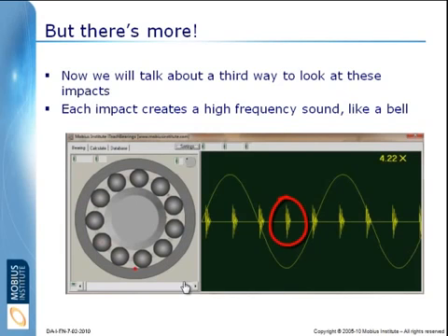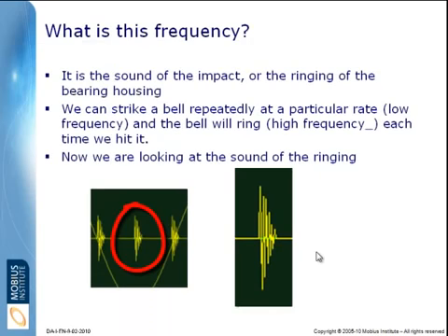Now, the third way is to look at or listen to the sound that is made when a ball hits the defect. We can think of the ball bearing like a bell, and when the ball hits that fault, the bell rings. And when it rings, it makes a sound, and that sound is a high frequency, and that's what we are seeing here circled. So let's look at this high frequency a little closer.